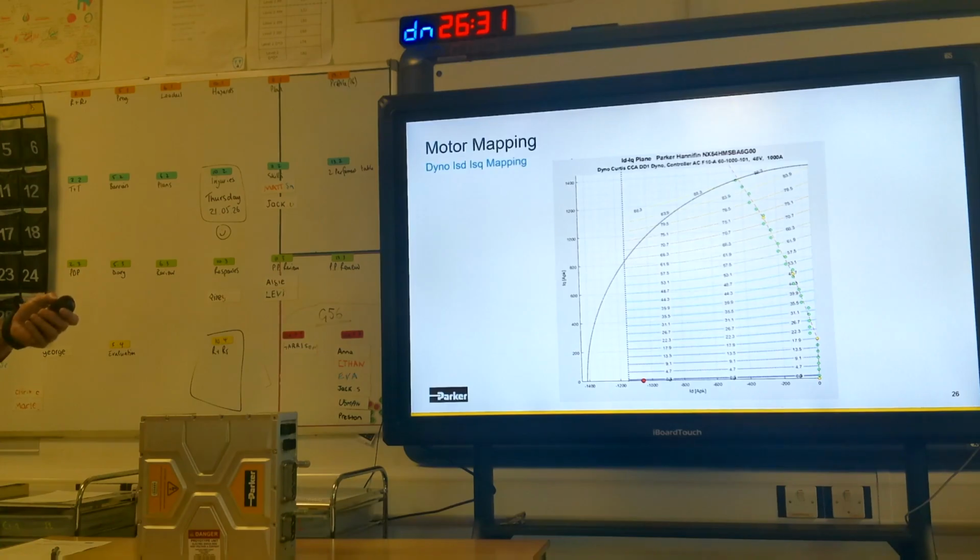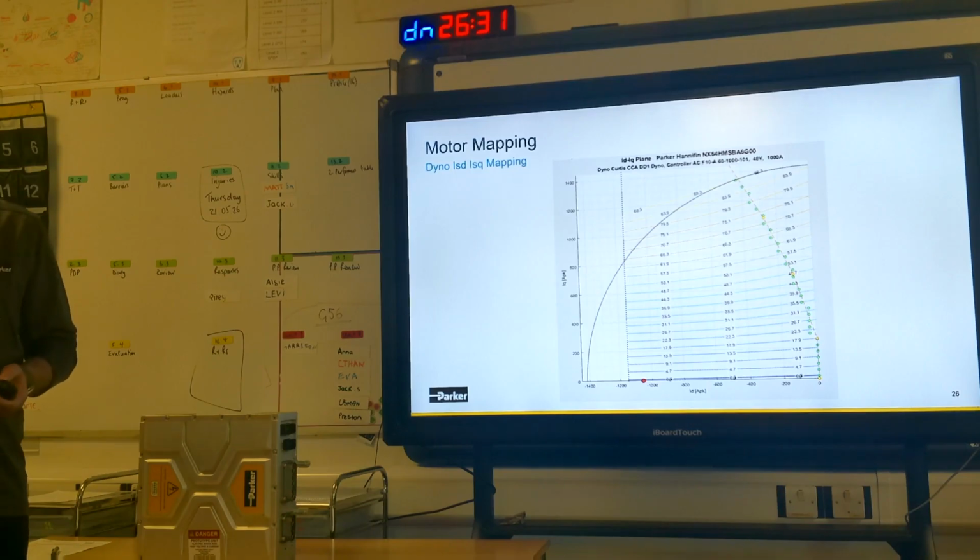Just on that one, will the characteristic drift very much over time? It will drift with temperature. Not time necessarily, unless the magnet demagnetizes or something like that, then it would drift over time. But assuming there's no demagnetization, the other effect that changes the strength of magnets, which is temperature, can have an effect on this.